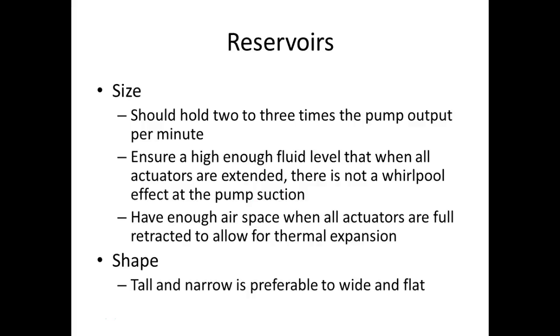The reservoir should hold 2 to 3 times the pump's output per minute, ensuring a high enough fluid level that when all the actuators are extended, there's no whirlpool that affects the pump suction. Just like in your bathtub, when you start draining it, the closer it gets to the drain, it starts spinning.